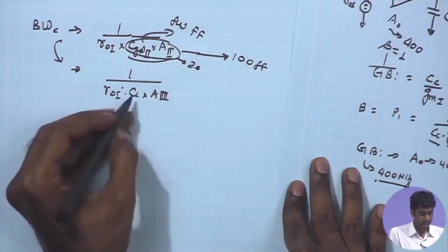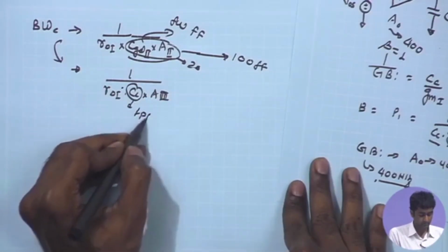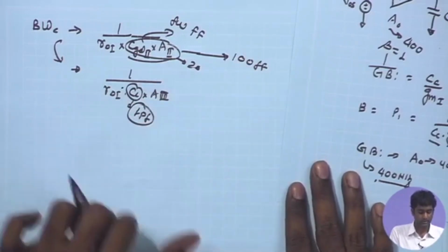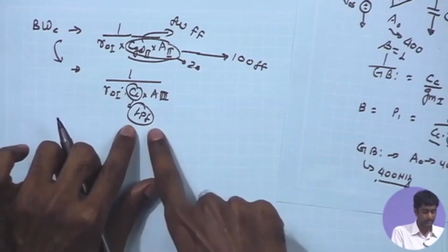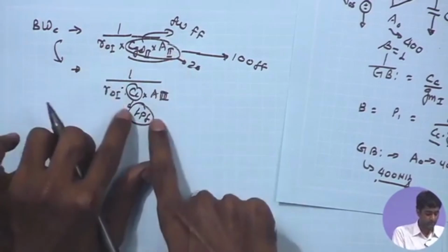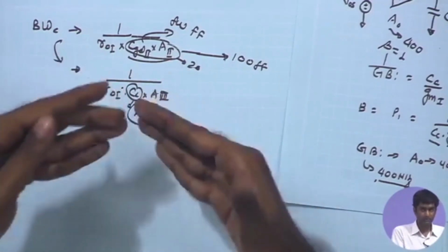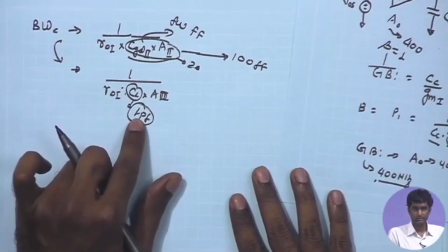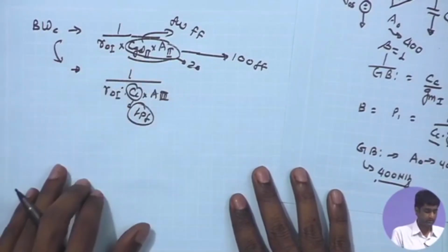Here this value we have chosen is 1 picofarad, right. So, of course, the capacitance has gone up by 10. As a result, if I am looking at the open loop bandwidth as compared to that, the open loop bandwidth of this voltage follower definitely is lower by this factor of say 100.